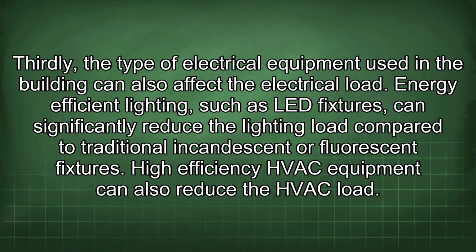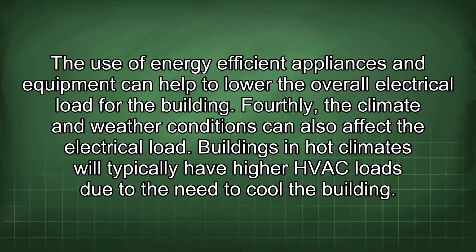Energy-efficient lighting, such as LED fixtures, can significantly reduce the lighting load compared to traditional incandescent or fluorescent fixtures. High-efficiency HVAC equipment can also reduce the HVAC load. The use of energy-efficient appliances and equipment can help to lower the overall electrical load for the building.